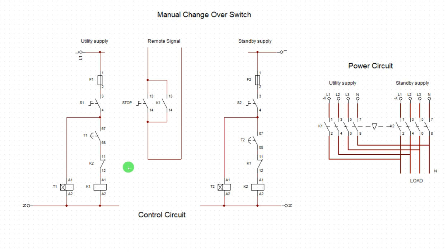You remember that a timer relay, like I said, is a composition of electronic chips, which is fragile. It's a fragile material. So if there is a vibration from this contactor, it may affect this. It may flash this timer because it's composed of fragile chips. So do not power a contactor directly from a timer. Even if the timer is a rugged type, don't do that. Always interface a timer with another electromechanical relay, which is a rugged type of relay. I taught you electromechanical relay. So let's do that now.